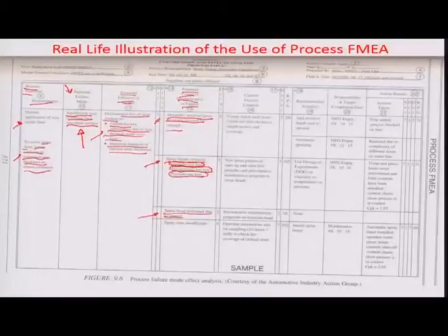Sometimes the quality engineer also observes a case of the spray head being deformed due to wrong handling of the gun. Guns are sometimes used to impact the doors to open them. You have to remember, it is a post electrodeposition process that we are applying the wax in. So there is always an ED oven and an ED tank involved, and there is a possibility that the doors might not open so well.